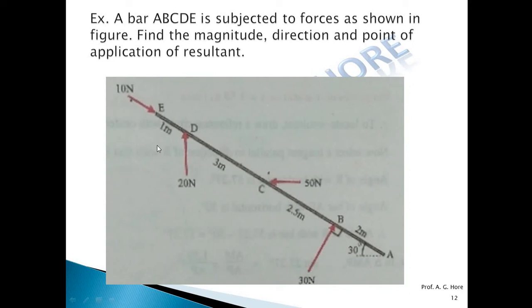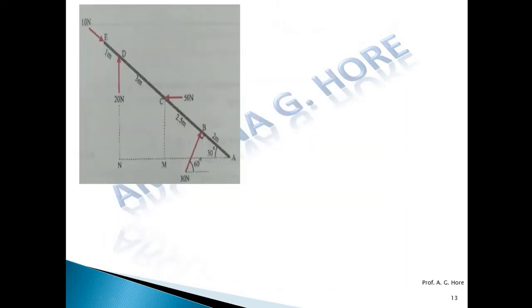Why are we using resultant R is equal to root of summation Fx square plus Fy square? Because here the number of forces are 1, 2, 3, 4, more than 2 forces, and these forces are not concurrent. So apply the second method, that is resultant R is equal to root of summation Fx square plus summation Fy square. That's why we are using that formula. These are the non-concurrent forces.